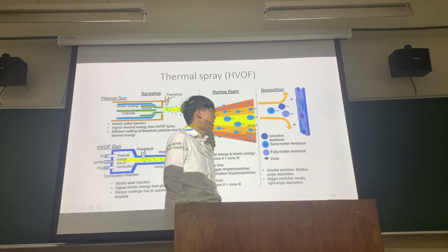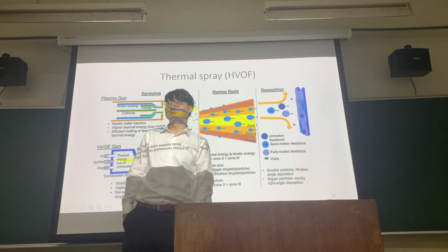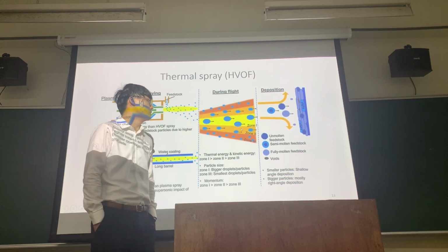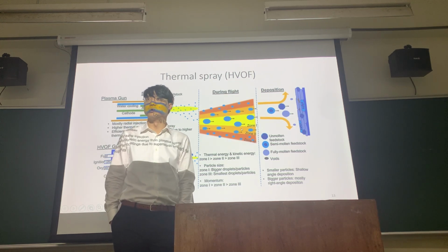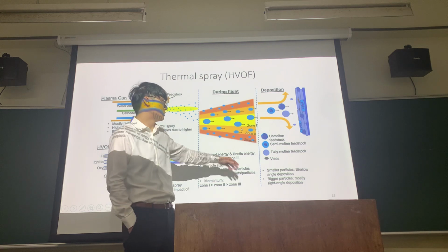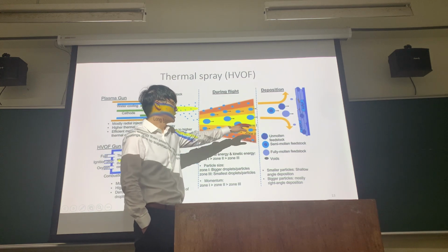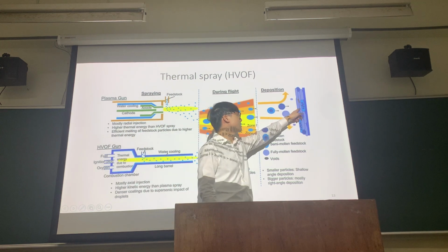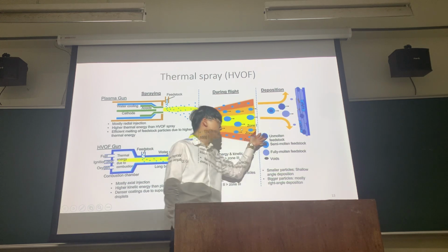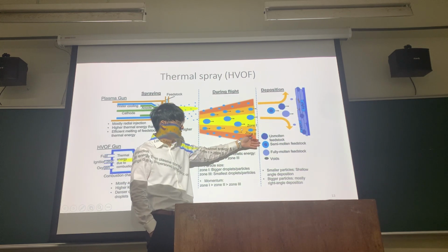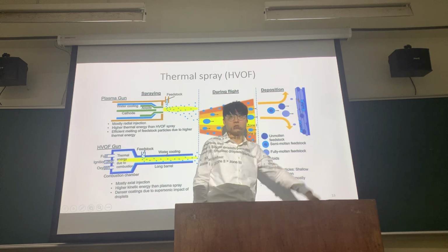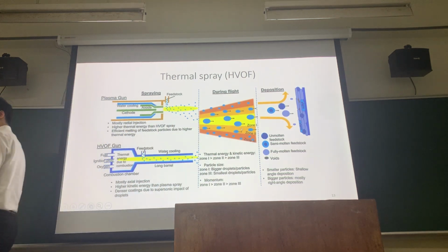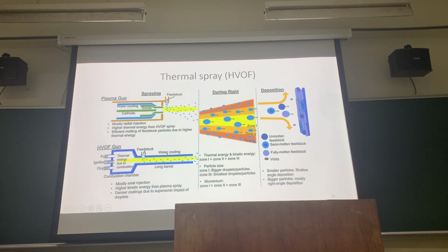This is where the void is being built up, or the porosity being built up, for those that are half molten or not fully molten materials. You can see this is where the porosity builds up over here. So over here you can just go and read: there's unmolten, semi-molten, and fully molten, right? Especially the semi-molten part is actually where the void is being built up. Okay? Questions?